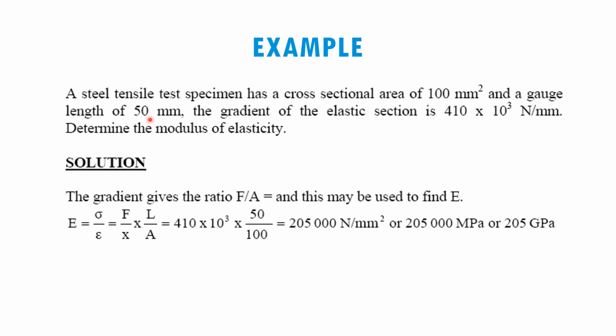a gauge length of 50 mm. The gradient of the elastic section is 410 times 10 to the power of 3 Newton per mm. Determine the modulus of elasticity.